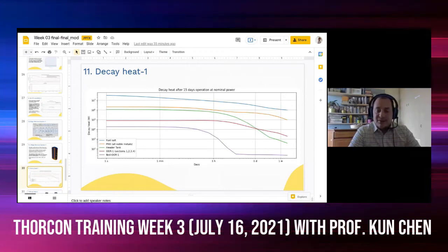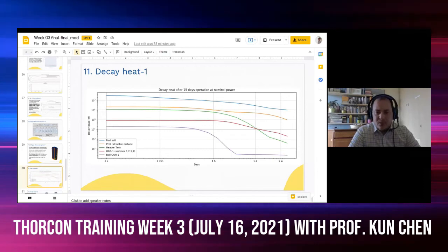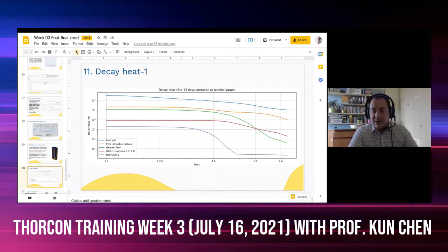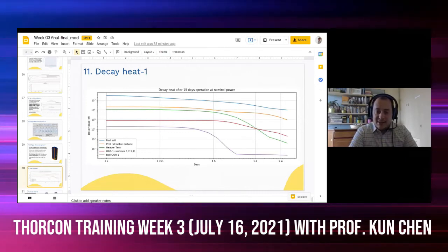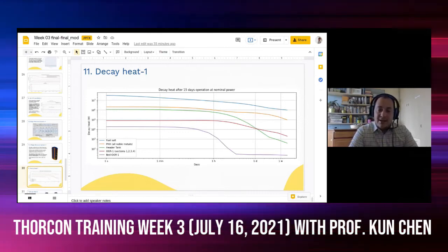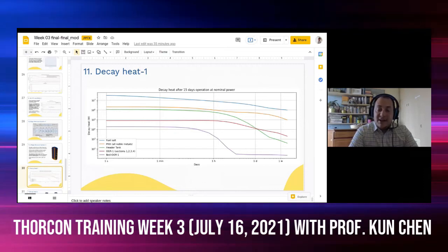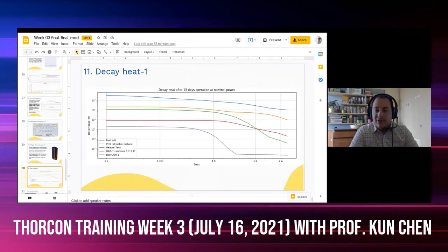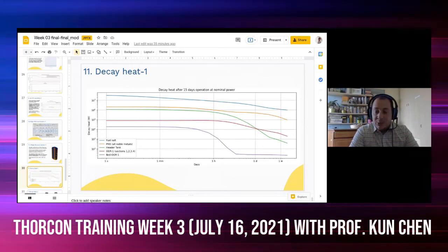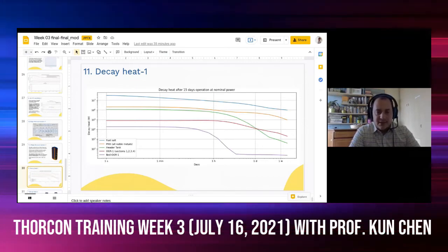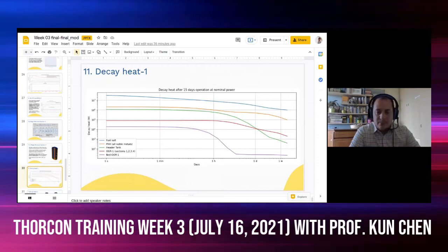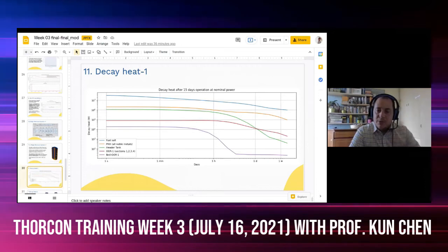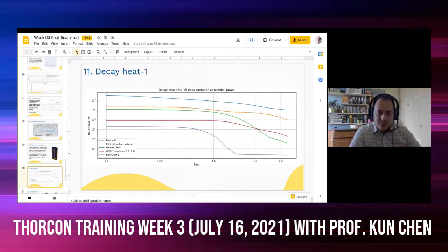These effectively change the heat transfer rate in the primary and secondary heat exchanger, as well as in the steam generator and in the steam radiator, effectively allowing the reactor to quickly follow the load with several percent per minute variation in the power without overshoot or extreme temperature variation.